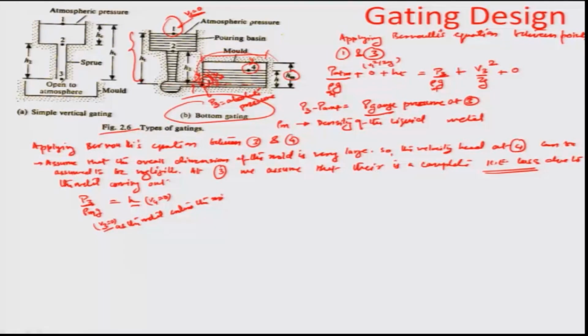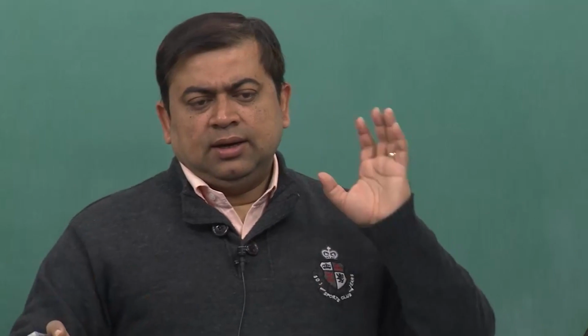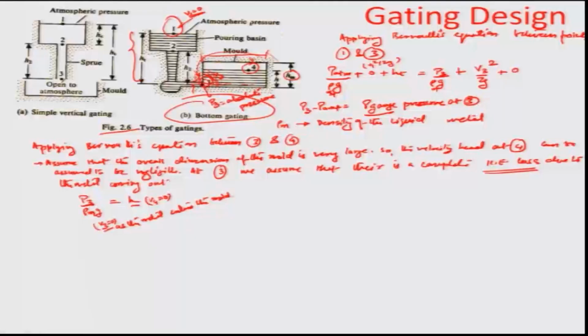So, this is just about the same instance of time, the only thing is it has just entered the mold from the cross sectional area, and we are assuming that the amount of kinetic energy delivery to the mold is negligible in comparison to the overall mold sizes, etc. So, sorry, the kinetic energy is negligible because of the overall largeness of the mold size, etc., and it is as if a few droplets are emanating from that small gate region into a bigger mass of fluid. Okay. So, the kinetic energy addition is very, very low, and so we are assuming this V3 beyond the gate region to be equal to 0 for that case.